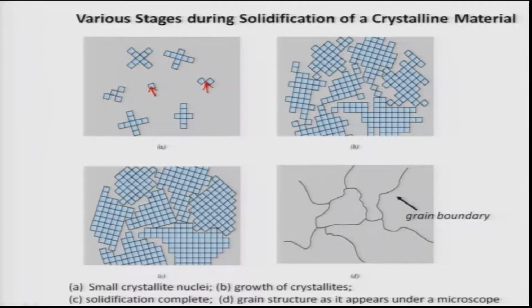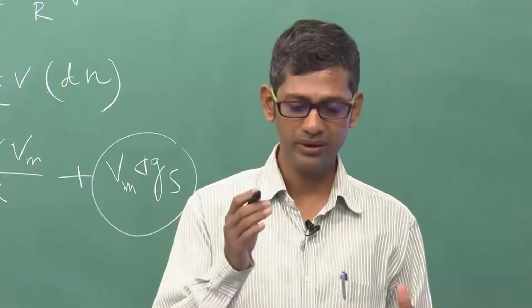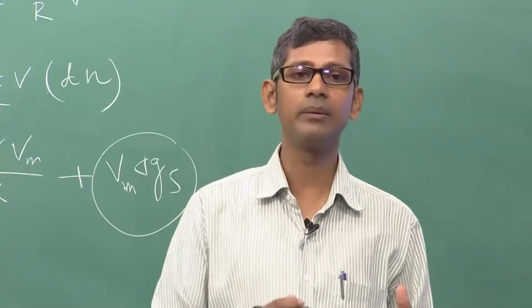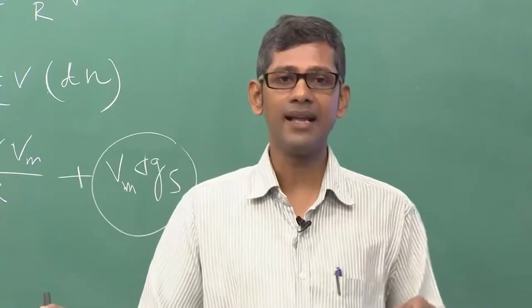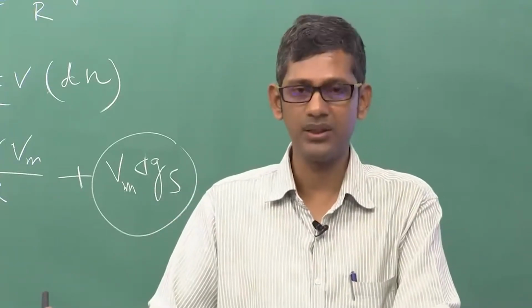Because of that, the atomic arrangements in the liquid and in these well ordered solids are distinctly different. Because of that, a definite interface is created between these clusters and the liquid, and because the atomic arrangements are different between these well ordered crystals and the liquid, there will be energy associated with the interfaces, and this energy is positive, just like surface energy.